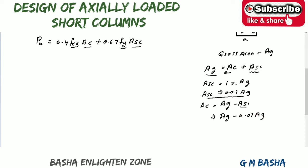So I am substituting in place of Ac, that will be equal to 0.99 Ag. So area of the steel is 1% of the gross cross sectional area. First assume that; based on that you will get the area of the concrete, that is 99% of Ag, so that is 0.99 Ag.